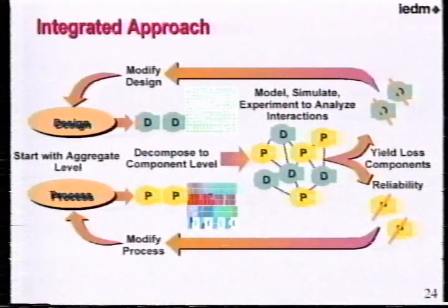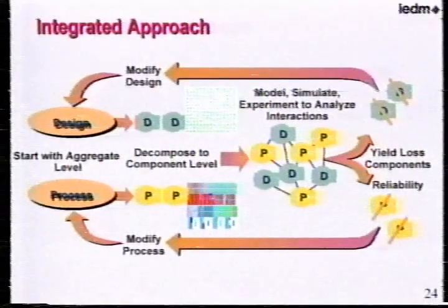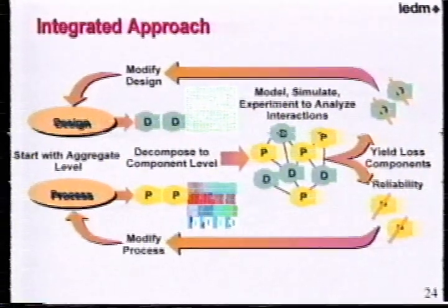Does it have isolated vias which fail a lot? Do you have long runner lines in poly where salicide break is going to be an issue? How is your SRAM going to be laid out? That kind of thing. You have library components, you have SRAMs that you run early on. You can even look at shrinks from your previous generation to see where the trouble hotspots are going to be.